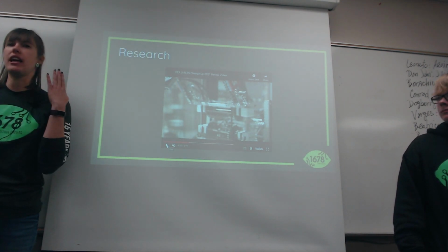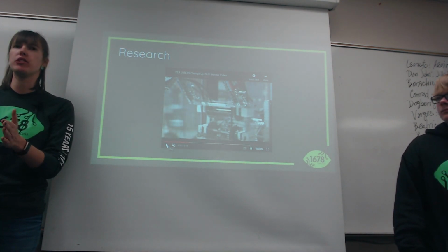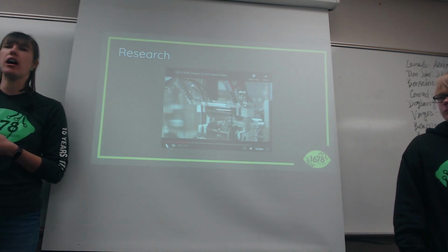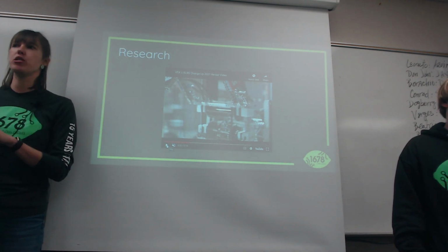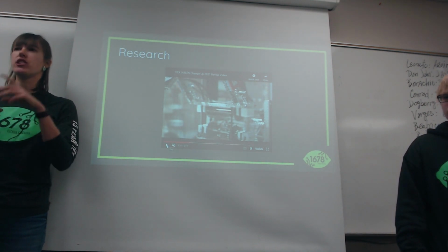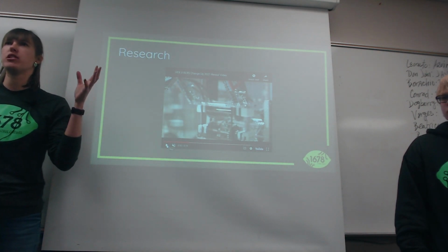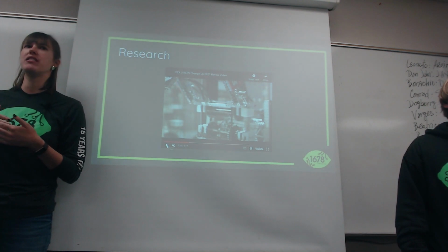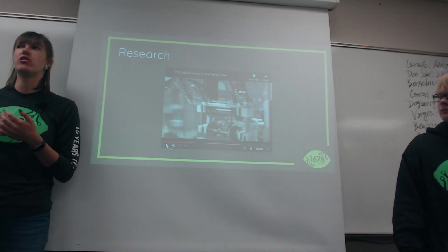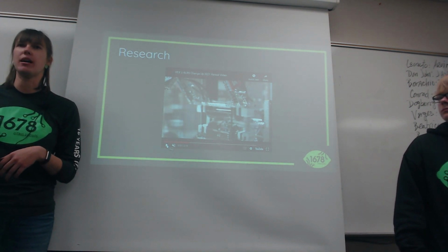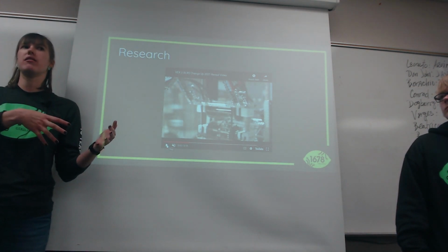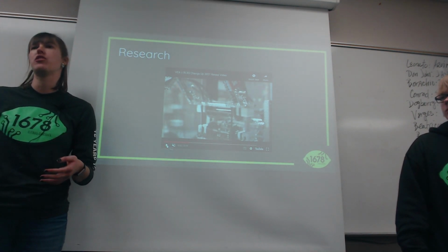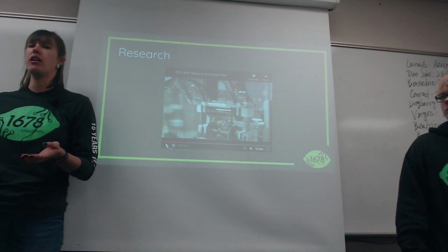It's easy to get really tunnel visioned on, I want my robot to be able to do this, but you really need to think broadly. For example, for this 2022 robot, there are red and blue balls on the field, and they're coming out randomly from the shooter at the top, right? If you want to be quick in picking up the ball, you have to have a way to get rid of a ball that you've picked up that's the wrong color. Because if you drive into a grouping of red and blue balls, you want to be able to ensure that you come out with the two colors that you want.